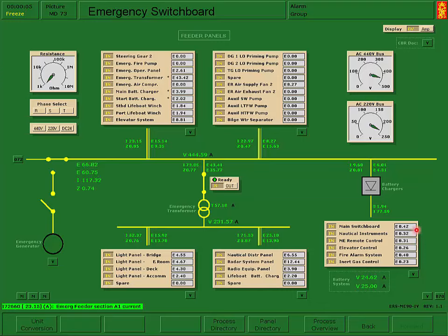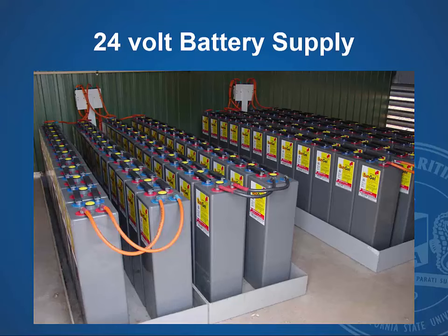On this, the standard on most vessels is 24 volts. Just as a warning, if you forget to put these on, the simulator is drawing current from these batteries and they will discharge fairly quickly. This main switchboard supplies power to your main ship service diesel generators' voltage regulator, and if the batteries drain, you will not be able to bring up power on the generator. So this would be an example of a battery backup system that you could see on a vessel.